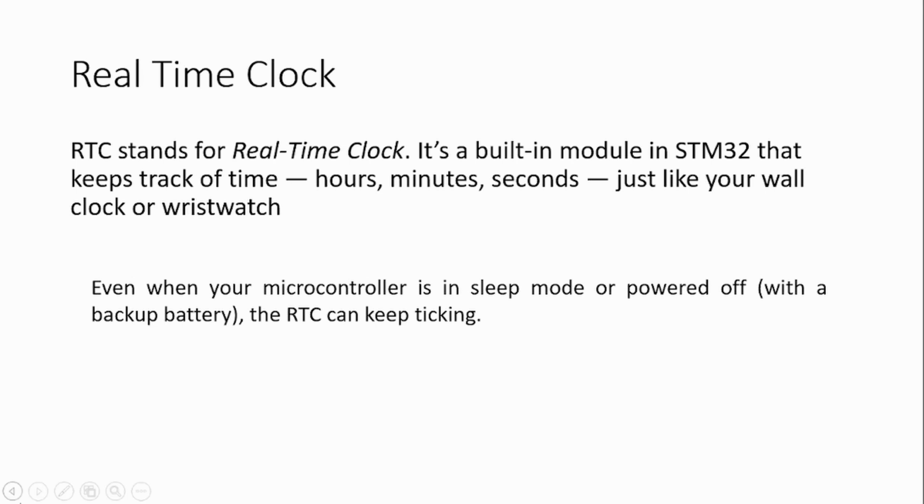Even when your microcontroller is in sleep mode or powered off, meaning power is not present for the microcontroller, if a backup battery is provided, which is the basic minimum requirement of RTC, then with the help of this battery backup, RTC can keep ticking, right? It can keep track of the time and date with the help of this backup battery. Even if the microcontroller is turned on or off, it doesn't affect the RTC, provided that the backup battery is available for the real-time clock.